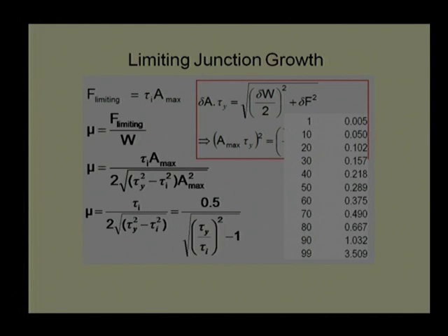Experimental results show that when two soft materials are used, their interface shear strength will be very high, almost equal to that of the weaker material, and the coefficient of friction can be very high, maybe 3 to 4, or the 3.5 we are getting from here, right.